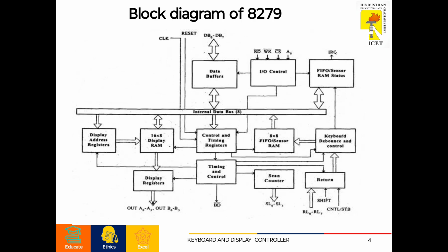Here, the output lines are connected to the anodes through a driver transistor in case of a common anode 7-segment LED. In this display section, there are two modes: one is common cathode connection, and the other is common anode connection. Here, we are using common cathode 7-segment LEDs, where the cathodes are connected to the scan lines through driver transistors.